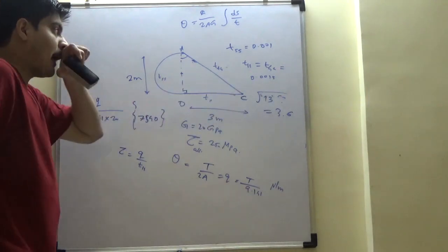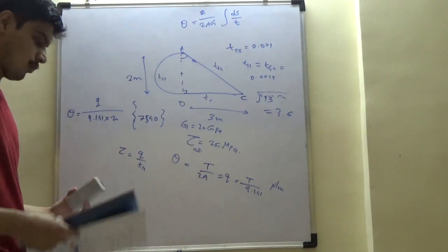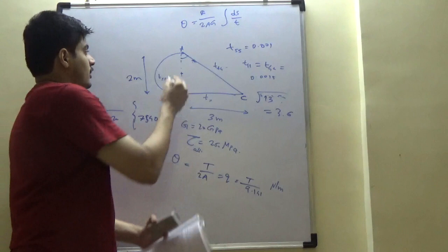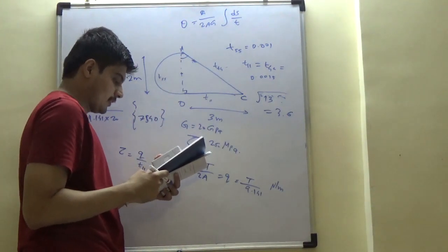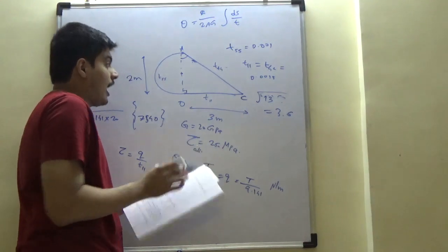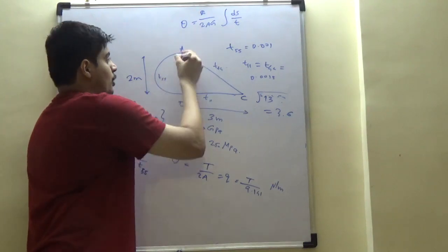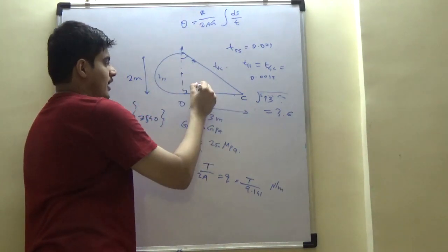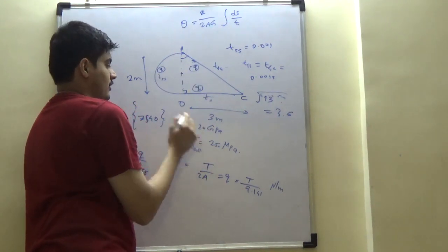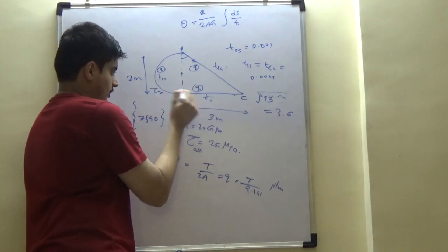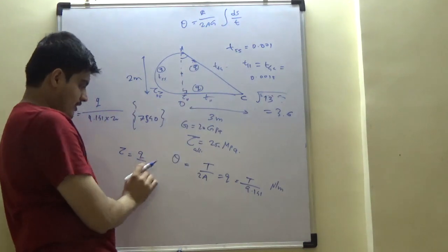The thickness which is actually minimum is where tau is going to be highest for a given shear flow. Here the shear stress is higher than the straight wall, correct? Which means I have to look at the least thickness, because the same shear flow is everywhere, and the stress is going to be more here. So tau 55 is more than tau 11 because of this relation.